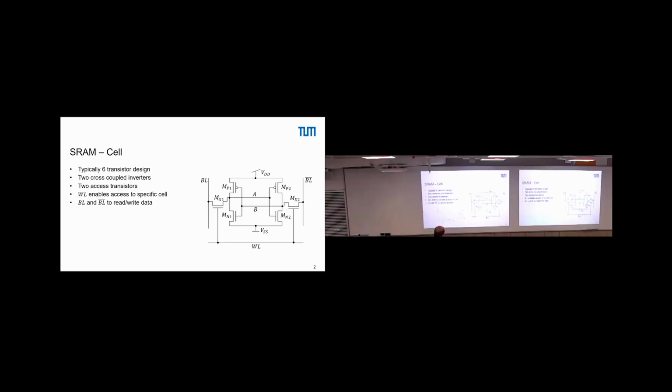So at the end state, the output goes down from VDD to 0. So here's actually the output. The output, this one here, goes from VDD at the beginning, at 0 volt input, to 0 at VDD input. That's just what an inverter is.